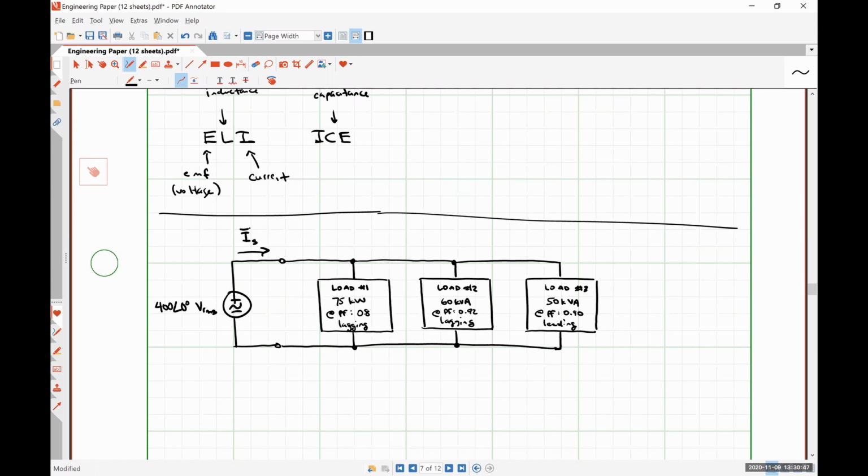Insulation melting is bad enough because that leaves you with potentials for short circuits and stuff like that. The wire itself melting is a good way to start a fire. So we would want to size our conductors such that they can handle the amount of current we expect it to be carrying. So figuring out how to solve for this current that's leaving our transmission line is literally a practical application of the stuff that we're learning here.